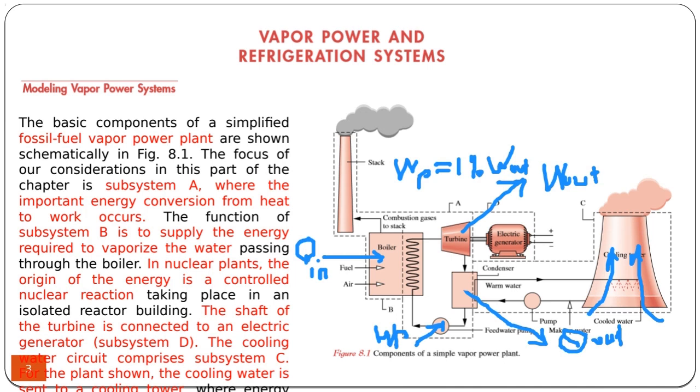And as the water is sprayed and evaporated, it absorbs some heat from the air. Because of this, we call it evaporative cooling. Let's say the water sent here is 35 Celsius, and it comes back to the condenser, just as an example, as 22 Celsius. So the amount of energy lost here is due to the vaporization of the sprayed water here.